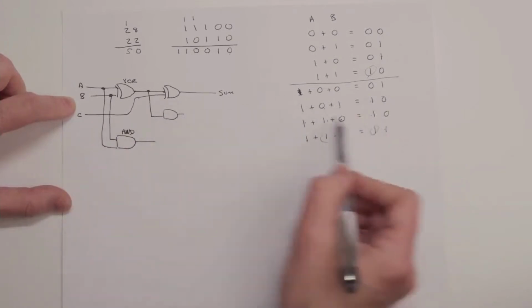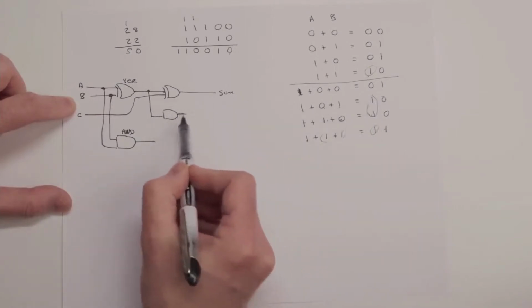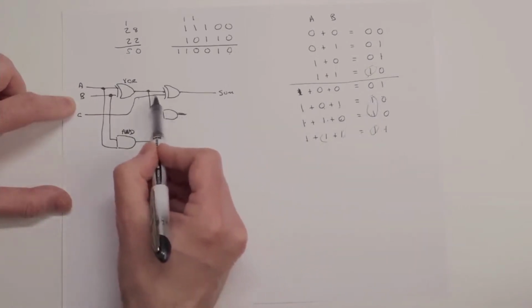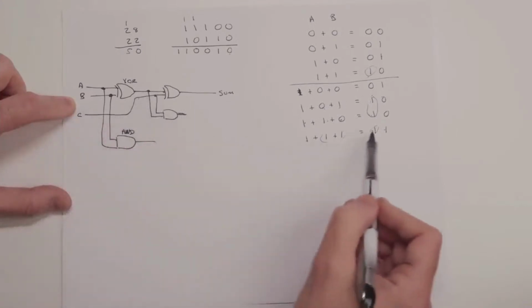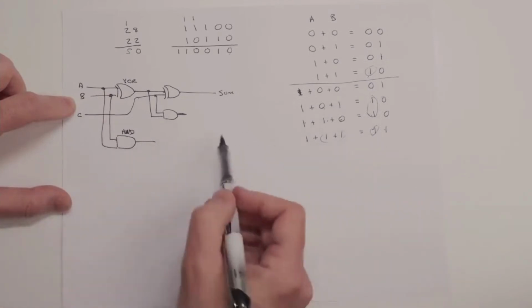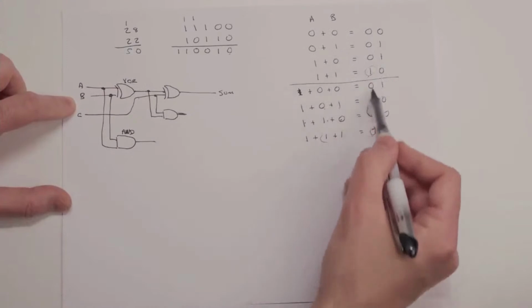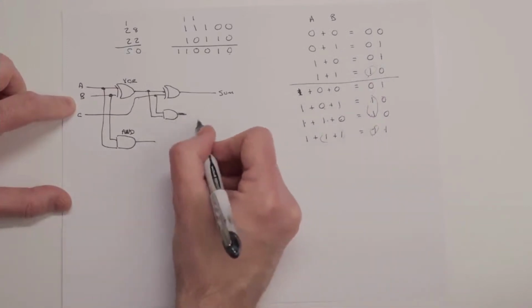So now we have this case. Now we have these two cases covered by this output of this AND gate. Whoops, we want to bring the carry bit in there as well. And we have these two cases where it's 1 covered by this AND gate. And so really what we want to do is we want to say that this bit is going to be a 1 either time this condition or this condition is met. So we can use an OR gate.